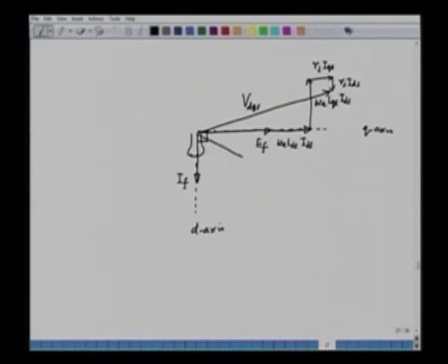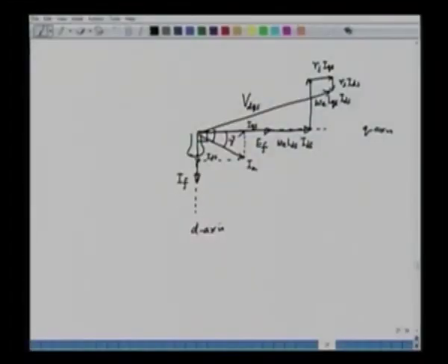The current is here, IA, and the current will have two components as we have already discussed. This is IQS, the q axis component, and this is IDS, the d axis component, and this angle is the angle gamma we have seen previously. So, this is the phasor diagram of a synchronous machine in the steady state condition, and here the power factor angle, the angle between V and I, we can call theta. So, this shows the various components of the voltage drop in the d axis and the q axis respectively.